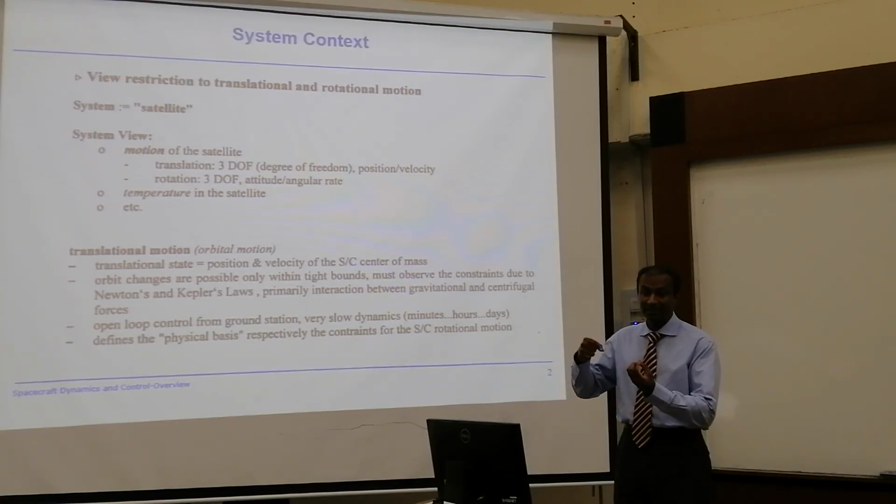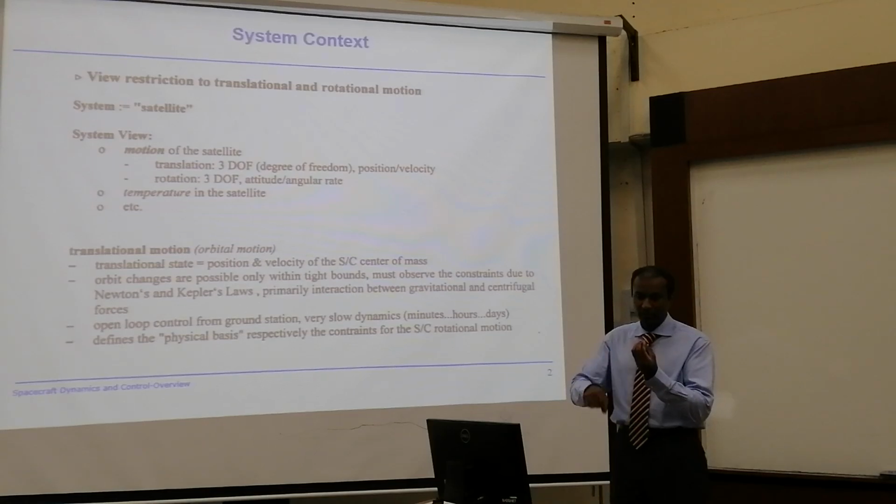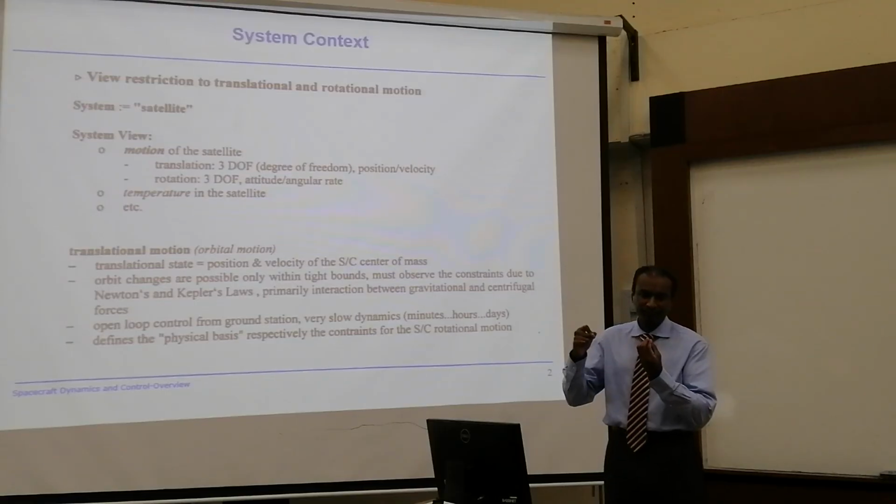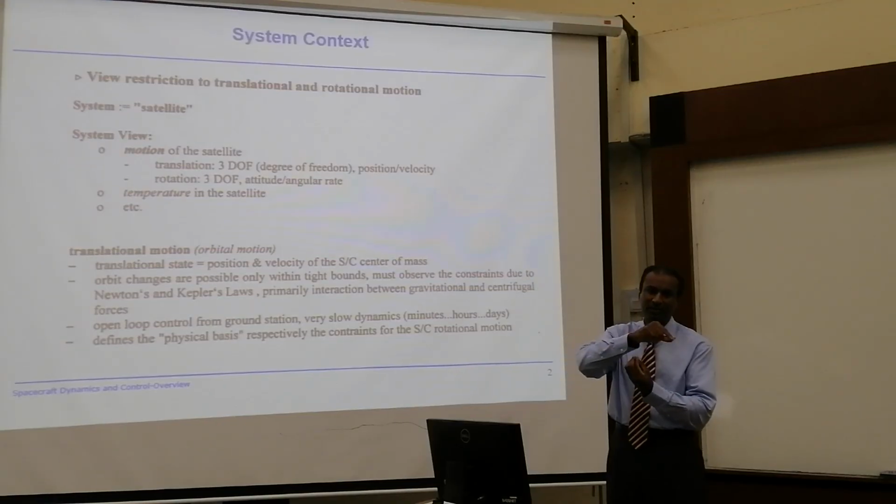And remember, your task is basically planet Earth. You know you can do a Hohmann transfer, and you know you can put it in basically the exact orbit. Then you ensure that the calculation of delta V is good enough for you to reach the orbit. So this is what you have calculated already. Good.